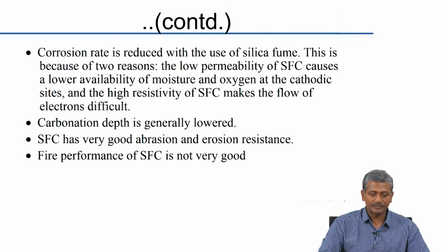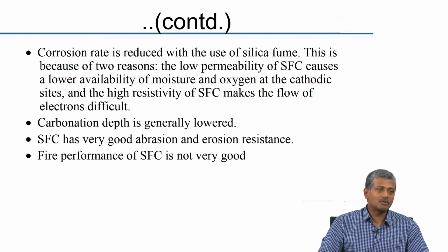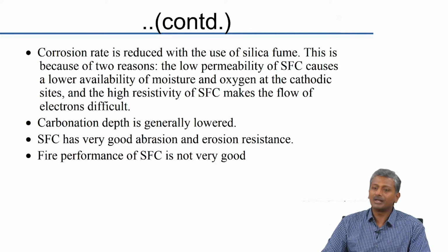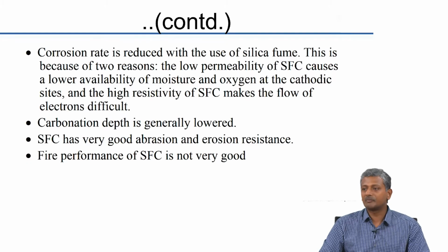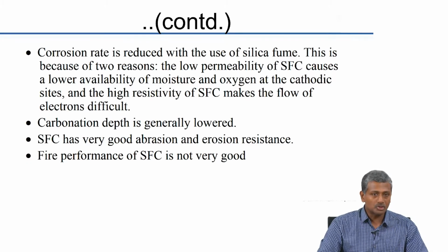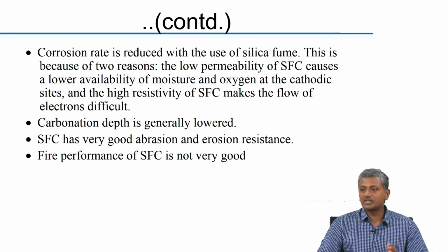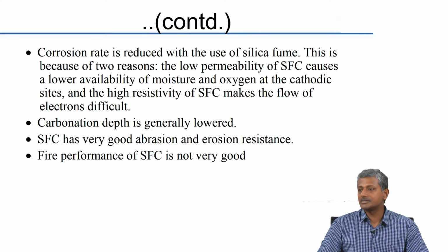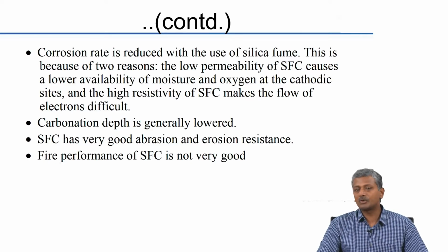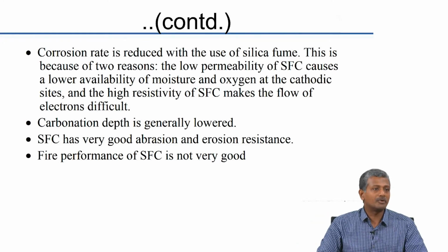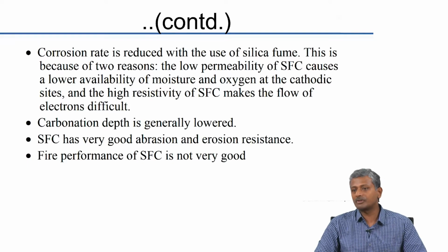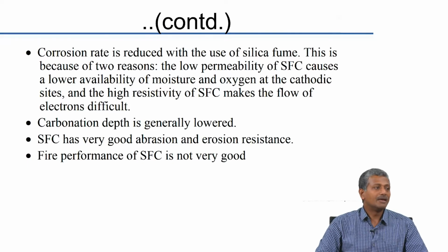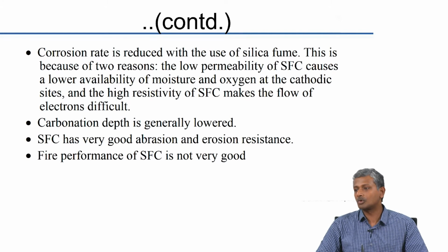Carbonation depth, this may be a matter of dispute, but in general it is lowered again because your permeability is of a much different magnitude, much lower as compared to ordinary concrete. Abrasion and erosion resistance are very good, and that is one reason why silica fume concrete can be quite suitable for applications in hydraulic facilities, wherever you expect a lot of aggregate or large boulders of stone to drop from massive heights. That causes a lot of erosion and abrasion on the surface of the concrete, and for that purpose utilizing silica fume could be a very beneficial thing.